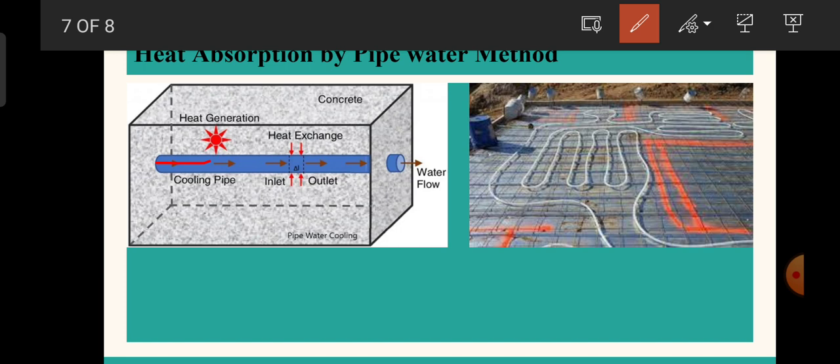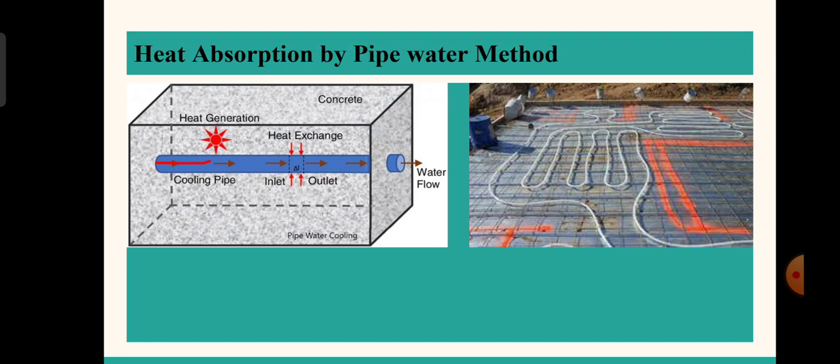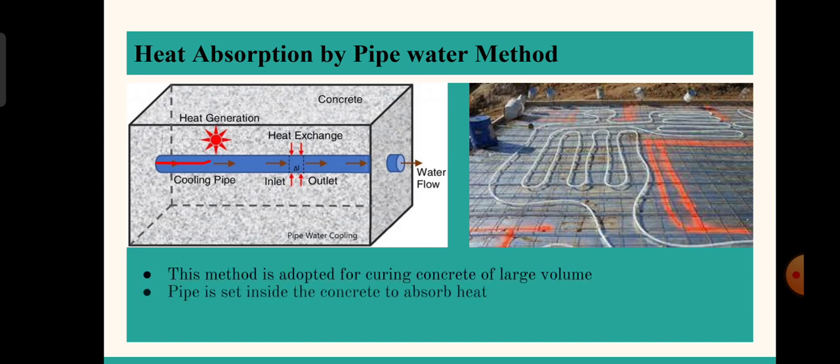Especially it is used for thick concrete made of higher grade used for construction. This method is more suitable for larger dimensions, and it is used to reduce the core temperature of the structure. However, these methods shall be used with much care, as a sudden change in temperature could cause cracking in the concrete. Continuous monitoring of the temperature of water also provides an idea about the internal temperature. Based on the observations, the flow rate of the water inside the pipe will be adjusted.